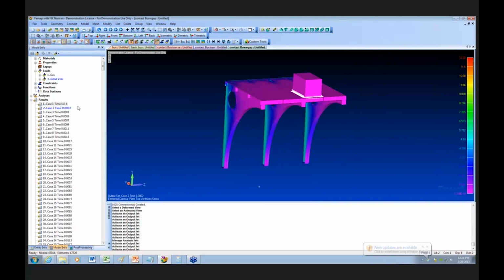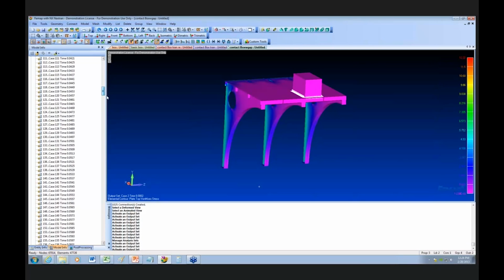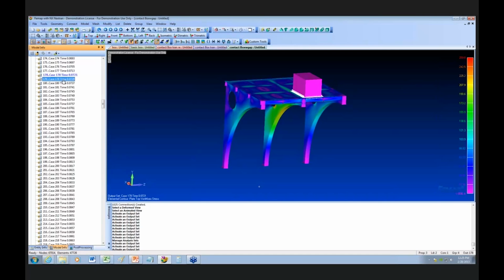So what it's going to do, I calculated it actually impacted at about 0.72. So I'm going to come over here, and we can see this is the unloaded stress for 1G, and we can keep coming down, and we see there's our impact right here. And the time's going to be different because I dropped it 1 inch. So if I subtracted 0.072 off of this, it impacted at 0.009 or 0.008 roughly.